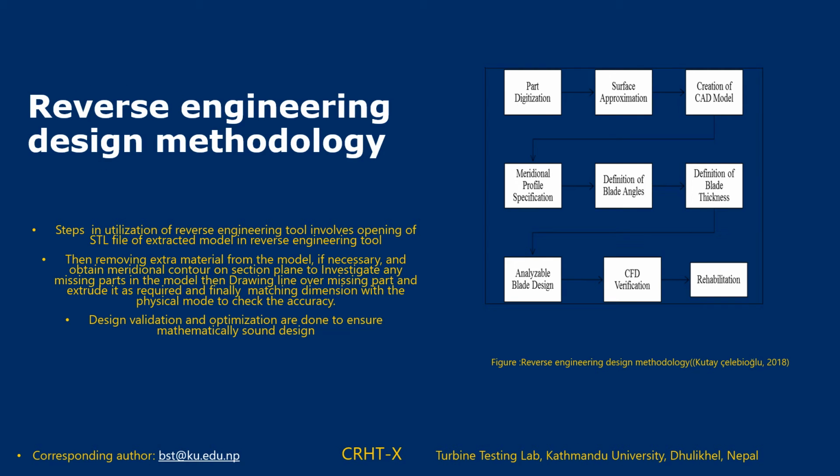So after 3D scanning of the runner, we were able to extract a CAD model of the eroded Francis runner. In this section, I will address the reverse engineering design methodology for remodeling of the eroded Francis runner. The pictures on the right side represent that the first step is part digitization, then surface approximation, then creation of the CAD model. All these first three steps are the 3D scanning process.